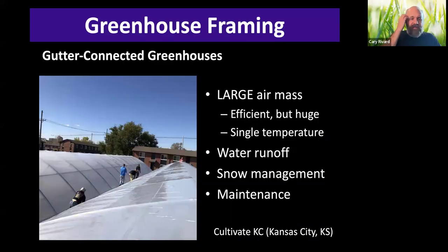Now, one of the nice things about these gutter connected greenhouses is that they have a huge thermal mass. You have a very large air mass there, so it's going to warm up slow in the morning and it's going to cool off fast in the evening. And those are both advantageous things because you don't want temperatures to swing very quickly in the greenhouse.